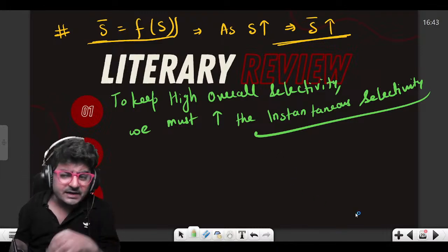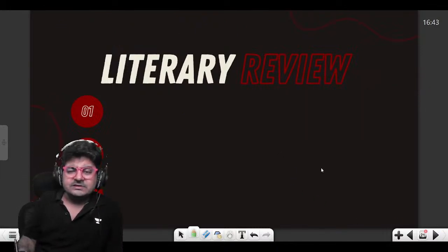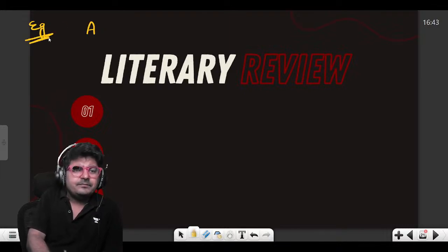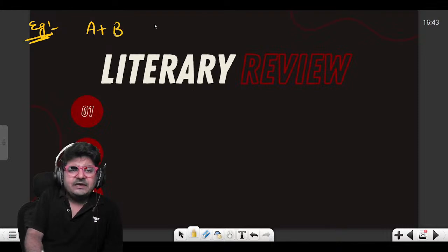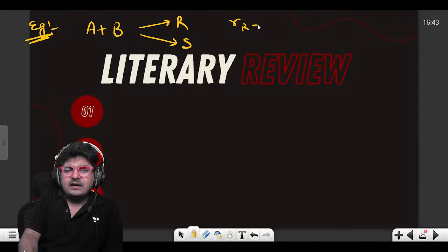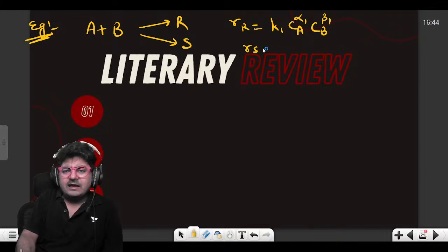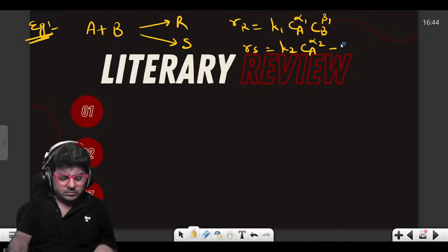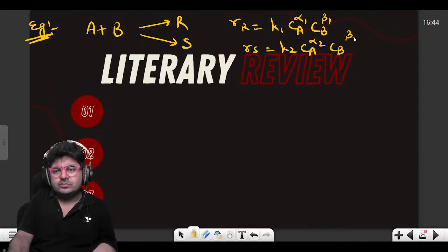अब वो कैसे करते हैं, क्या कर सकते हैं, वो देखते हैं. तो इंस्टेंटेनियस सेलेक्टिविटी की बात करते हैं. सपोज हम एक रिएक्शन लेते हैं. फॉर एग्जांपल, A plus B gives R, A plus B gives S, where RR is equal to K1, CA power alpha 1, CB power beta 1, and RS is equal to K2, CA power alpha 2 into CB power beta 2.